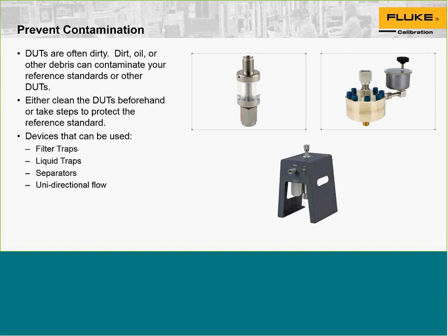A gauge that is full of oil, and you run your system, even if you have a gas system as your reference standard, then you connect the next device, and the oil from the first device under test gets into the system and then exposes other devices to that oil as well. This causes major problems. There's ways to tackle this issue. One often done is to clean the devices under test beforehand, or you take steps to protect the reference standard in other ways.